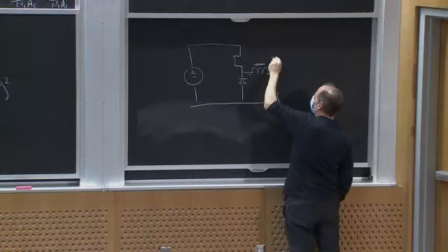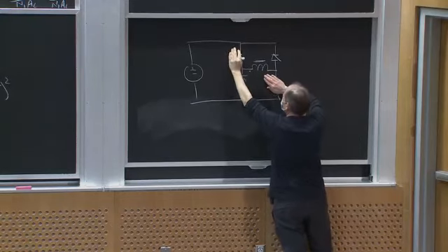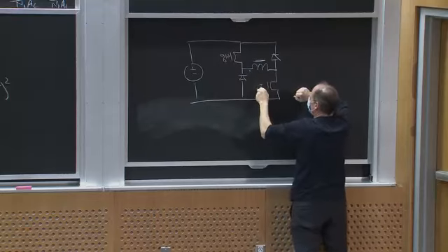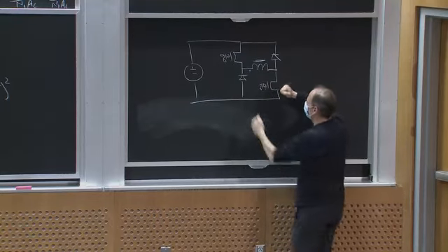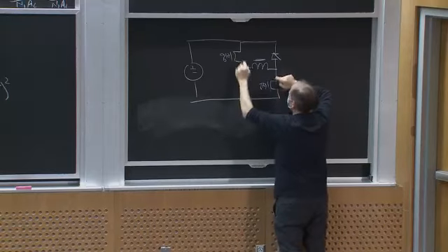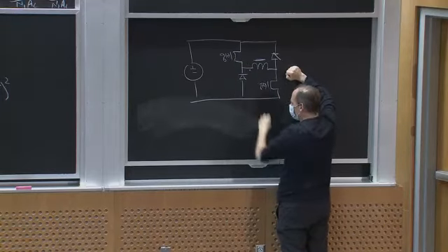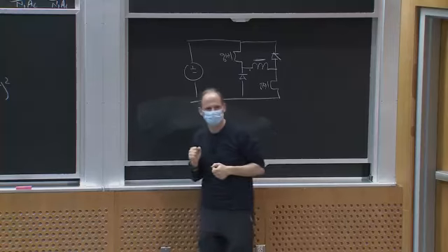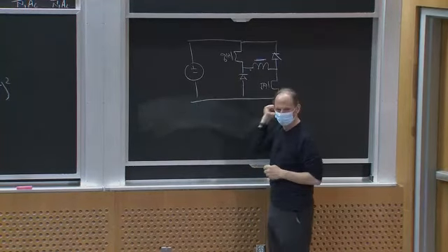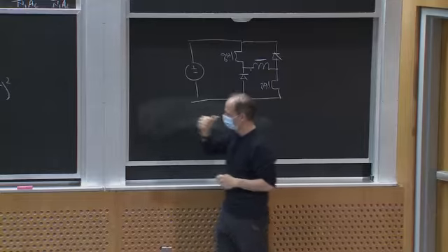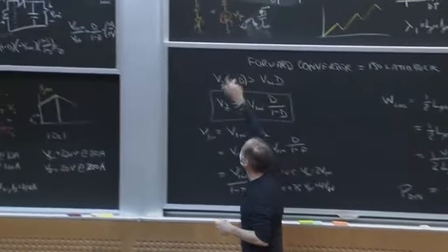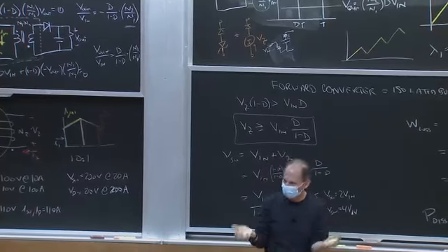And in the second part of the cycle, I'll turn on this, this is Q of T, and this is Q of T. So I apply a positive V_in across the transformer, just the way I did up there. In the second part of the cycle, the switches turn off and the diodes turn on, and I return the magnetizing inductance energy to the input. This can work up to a duty ratio of 50%. Or I could create another winding, and instead of throwing the energy into a Zener diode, I could throw it back to the input. That's another way I could do it.